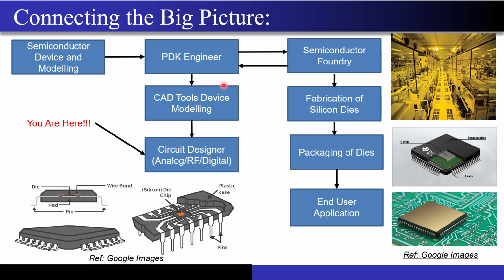So first of all, let's understand what this PDK engineer does. See, it's a different thing that I'm designing the circuits on the simulator, but somebody has to ensure that if I fabricate a transistor, right, let's say I do a very simple circuit, the common source amplifier, and I got some results on the simulator, maybe Cadence, correct? I got a very good gain around 15 or 20 dB, something like that. I got the unity gain bandwidth, whatever I wanted. Now somebody has to ensure that when I fabricate that transistor, it will meet that performance. Its IV characteristics will not deviate a lot from what the simulator is predicting, correct?